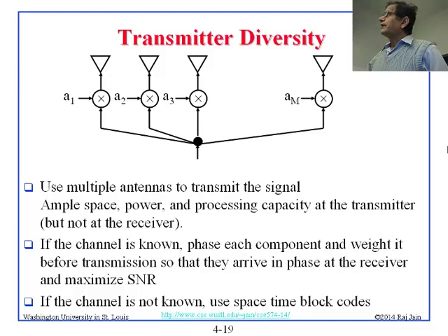and then at the receiver you could see where you are getting the best one, and you could do similar combining like you did before. You can take the best received signal, or you could take the best phase, or you combine all the phases, things like that, right? And if the channel is known, then you can do some mathematics. So this is where that formula we talked about, channel model, output frequency spectrum equal to input frequency spectrum times the channel frequency spectrum plus the noise. They use that formula to figure out how to combine all of this.